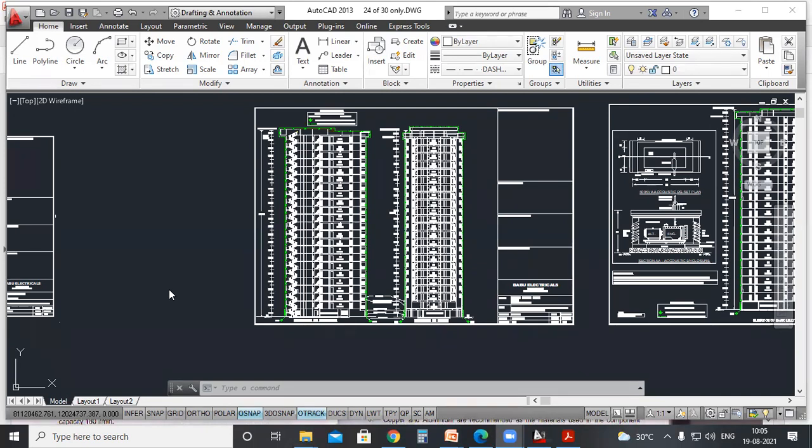There are some factors we need to understand. If lightning protection is required, then we need to calculate the number of down conductors, the air terminals and the earthing pits location, etc.